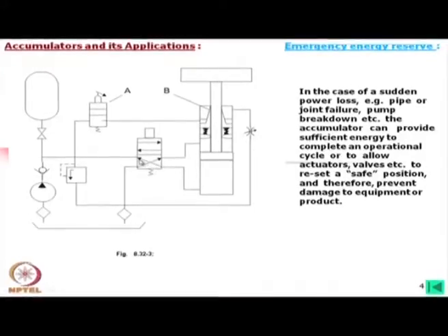And if it is connected like this, in that case this oil is going to the accumulator, of course, within the pressure setting of the relief valve, and the oil on this side, perhaps this arrow could be in this direction, is going back to the tank. Okay. So, this is just to protect a system in case it fails. So, this is one application of such an accumulator.